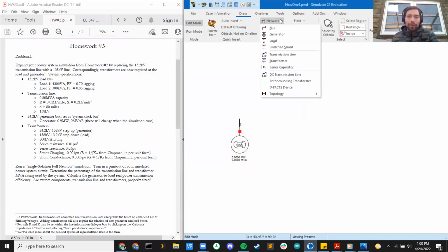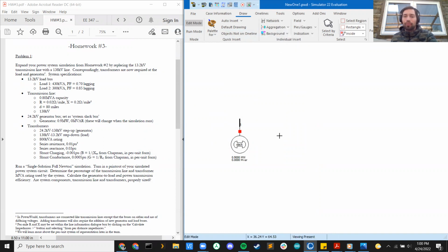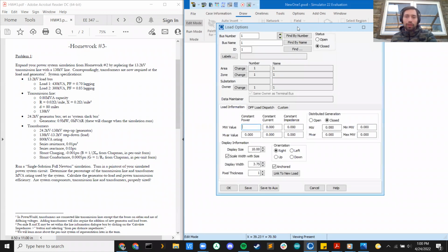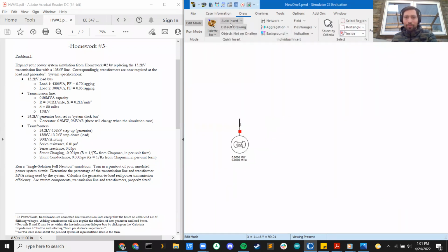So right now is where we start kind of new stuff for adding transformers in your system. I'm going to have to add a total of 3 more buses. If we were doing just the transmission line route, we would only need 1 more bus, the load bus. So I'm going to start off with our first transformer bus. It's a normal bus. You don't have to make anything special because it's a transformer bus. Oops, I pressed the wrong one.